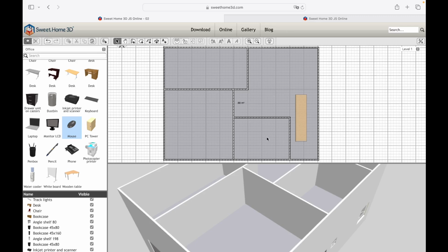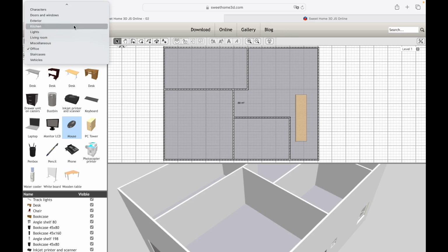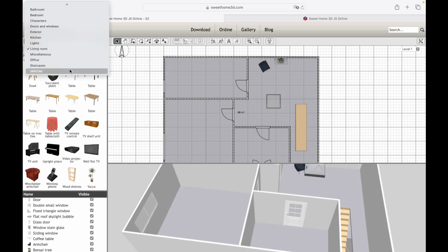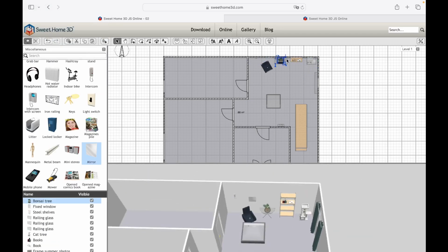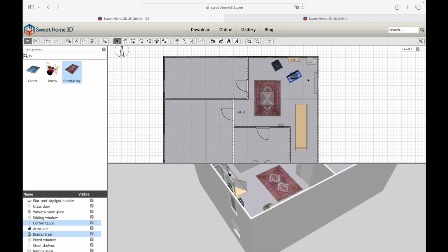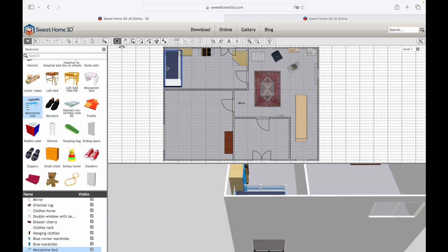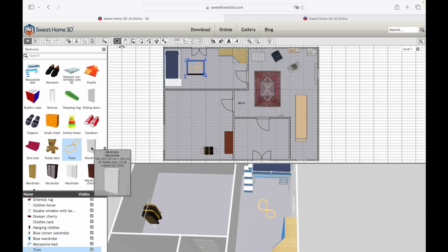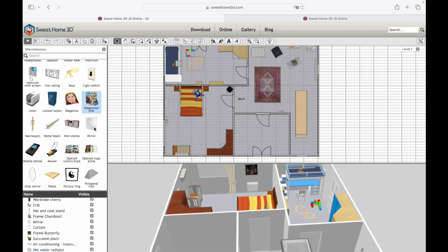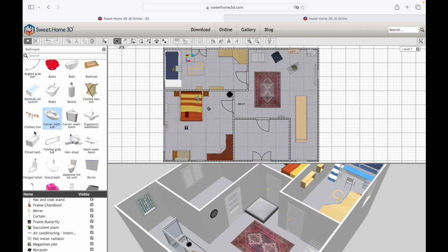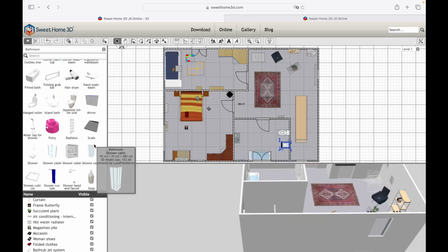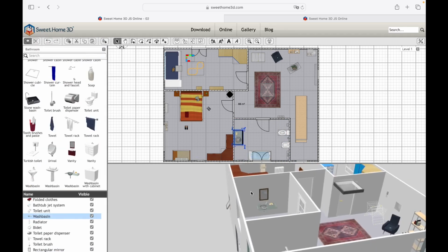As shown in the previous guide, we furnish the rooms by inserting doors, windows, and objects, selecting them from the drop-down menu, clicking, dragging, and dropping. With the Select Object in Plan tool, we arrange and modify the objects to our liking. For more information on how to insert and modify furnishing objects, I recommend you consult Lesson 03 of the course published on the channel.